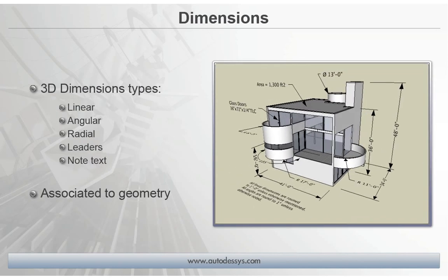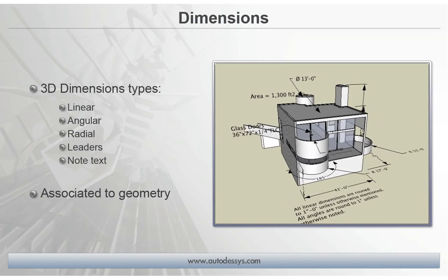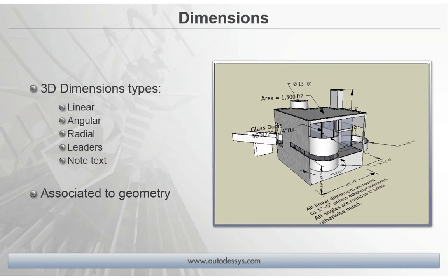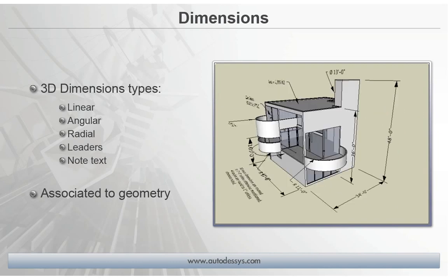Dimensions, 3D dimensions. You can add those anywhere that you want on your model. And it should be noted that these are associated with the object. So if you were to reshape the object or modify it, you can see that it'll then update that dimension. All right.